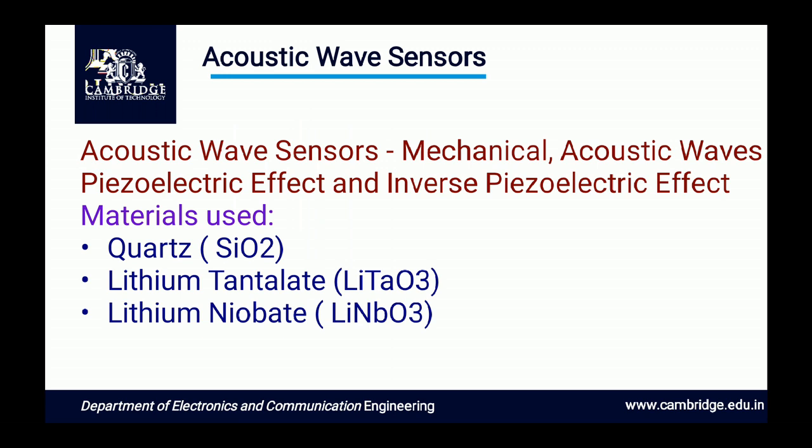And this phenomenon is reciprocal. That is, on application of an electric field, if it is converted into a mechanical deformation, then we call it an inverse piezoelectric effect. The piezoelectric substrate materials needed in sensing acoustic waves are quartz crystal in its crystallized form, lithium tantalate, and lithium niobate. And lithium niobate is less used compared to quartz crystal and lithium tantalate.